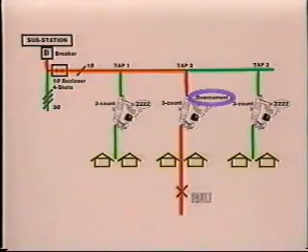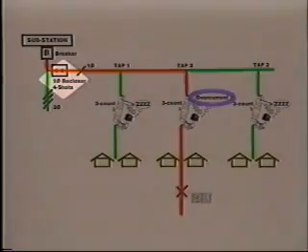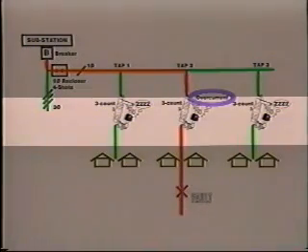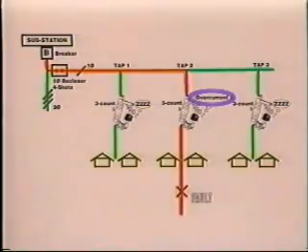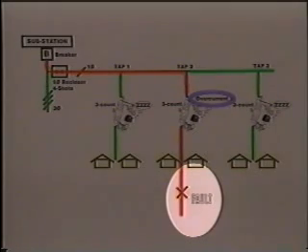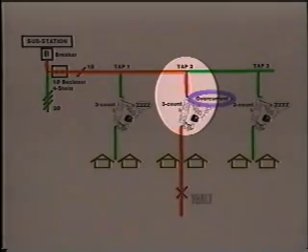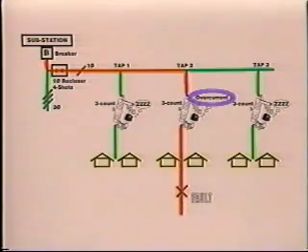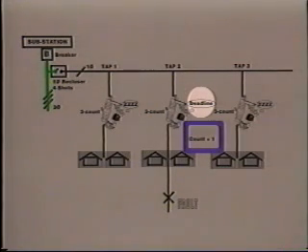Going back to our original example, let's assume the fault current is high enough to trip the 4-shot single-phase recloser, and all of the sectionalizers are 3-count devices. Remember, the fault has just occurred and the CES has just been alerted on Tap 2. The next occurrence is the single-phase recloser will open and satisfy the second event, dead line.